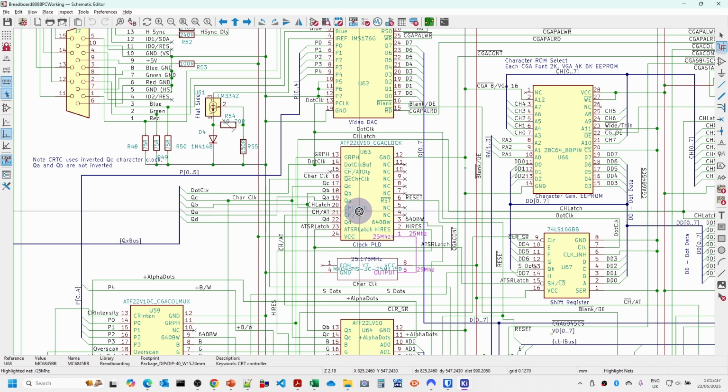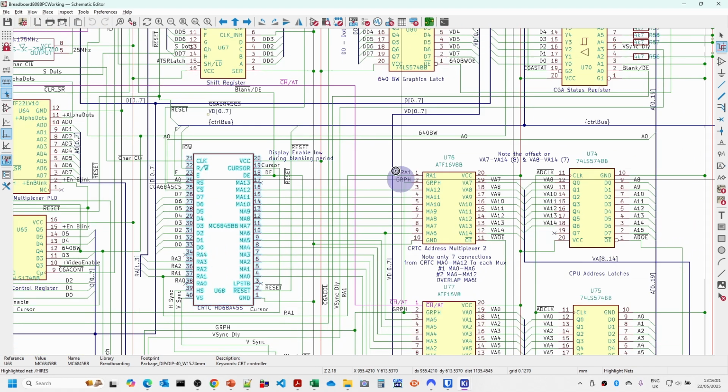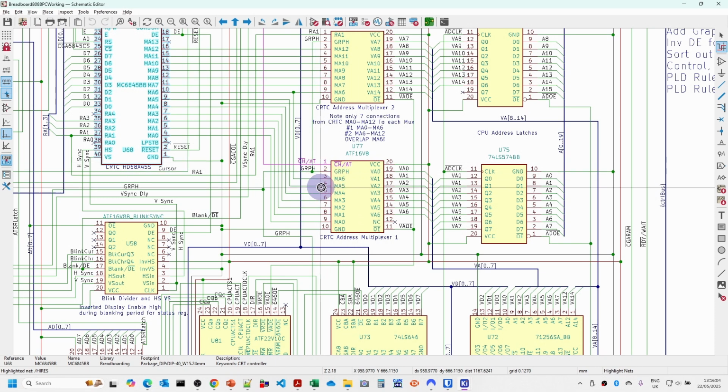And this is also generating the character latch, the attribute shift register latch, and the character stroke attribute value. So this switches between using the character byte and the attribute byte. This is modified slightly from the character clock, and that's actually used to drive the video here. So depending on the video mode, then this will actually drive video address line 0.